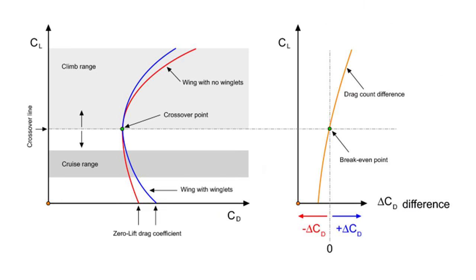In simpler terms, at higher airspeeds on larger and more swept back wings, the spanwise velocities on the wing will be comparatively stronger and will, at some crossing point, see the Horner wingtip no differently than a plain rounded wingtip. At this crossing point, the larger full winglet will be necessary for any further span-restricted efficiency gains at high lift coefficients. It's also worth noting that the weight fraction of a winglet on a commercial airliner is much lower than that of a small aircraft, and adding a winglet to the lower aspect ratio minimally swept wing that you would see traditionally on a small aircraft would meaningfully decrease any payload capacity at the expense of a likely negative efficiency increase.